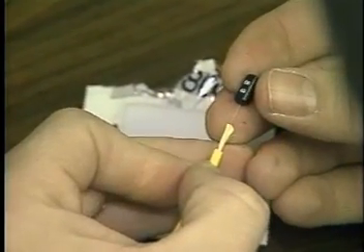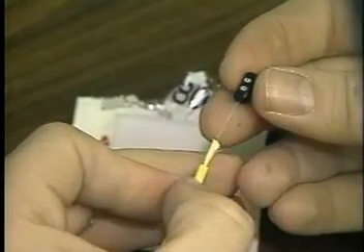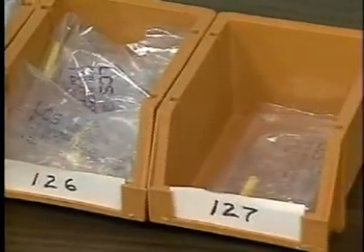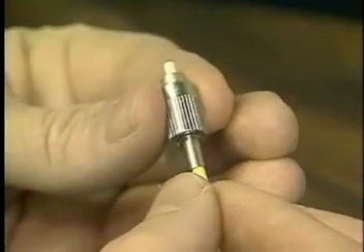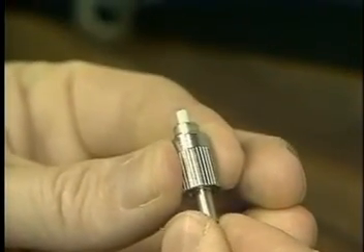When installing connectors, a cladding diameter of plus or minus 2 microns may require up to 5 ferrule sizes to be kept on hand. Otherwise, excessive space between fiber and ferrule would again result in unacceptable losses. Fiber cladding diameters are established during the drawing process. Today, manufacturers produce single-mode fibers with plus or minus 1 micron accuracy.